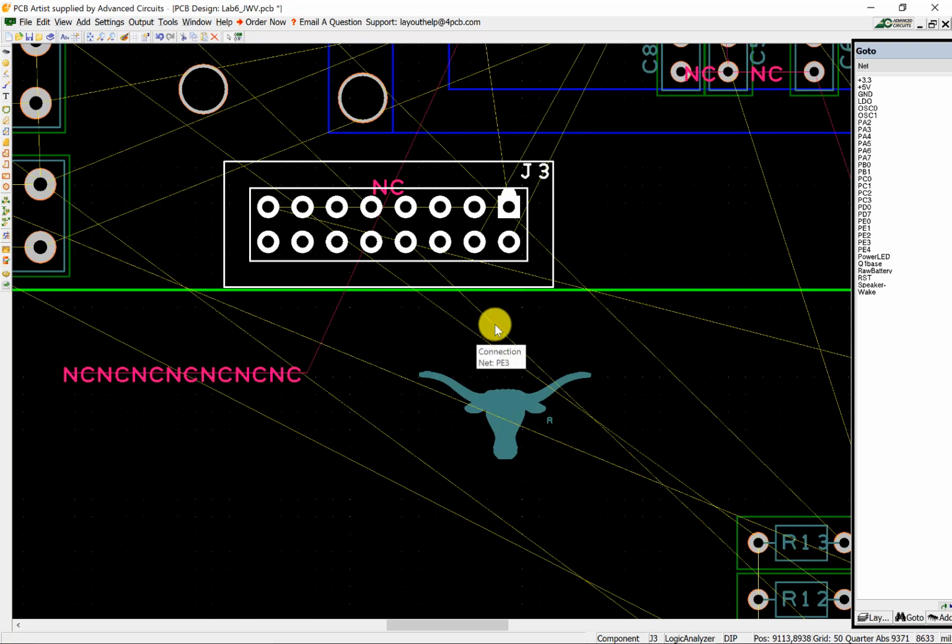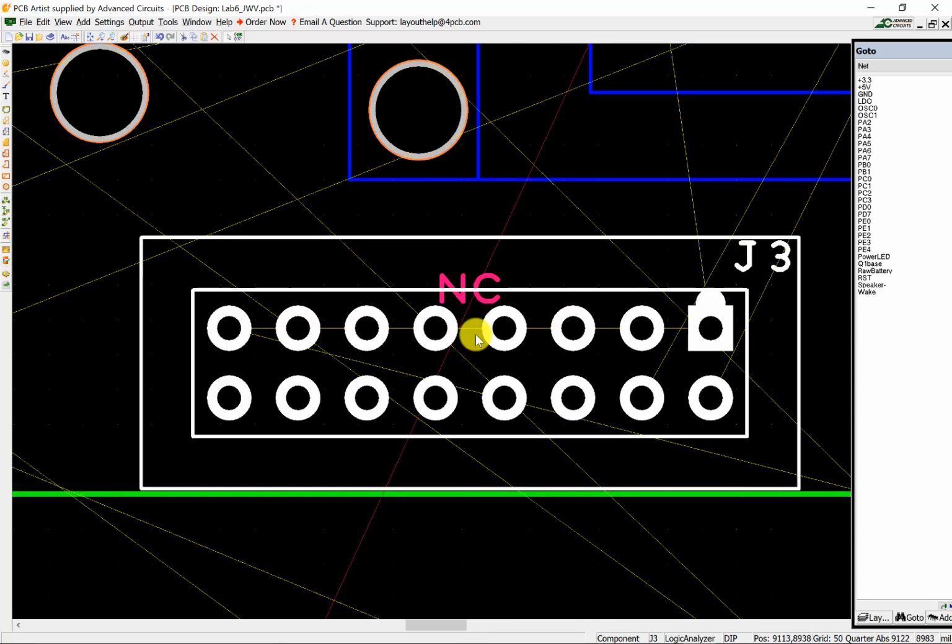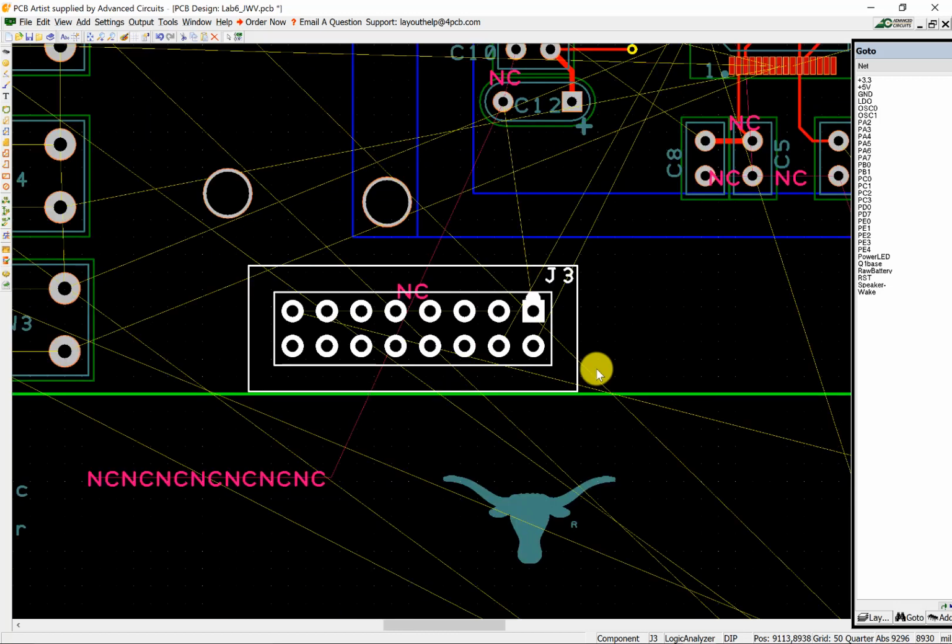The way the logic analyzer works is if you come straight in, this logic analyzer is actually going to be poking down, which is okay. If you put a right angle on it, then you can have it poke out. But if you're going to put a right angle on it, these lines here have to be ground. Because you don't want the right angle to go in, you want the right angle to go out. But you can have it on the other side of the box, if you want it to come off the top of the box. I don't care. All right, unlock that one there.